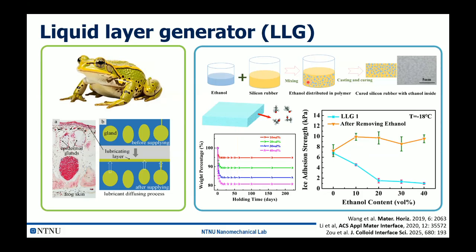So in parallel with the macroscale crack initiator, we also have lubrication at the interface, which will further reduce ice adhesion. And here I chose a really extreme liquid lubricant: ethanol, because ethanol has a freezing temperature of minus 126. So at a very low temperature, like in Arctic operation, where the material design temperature is minus 60, it will still keep the liquid state.